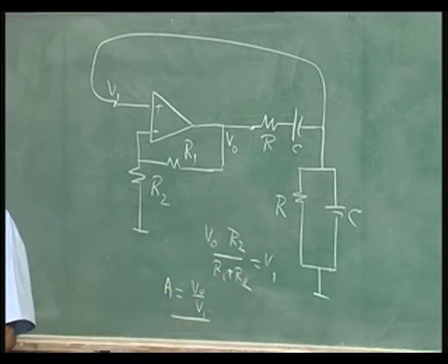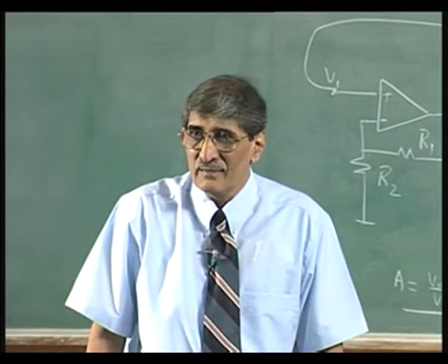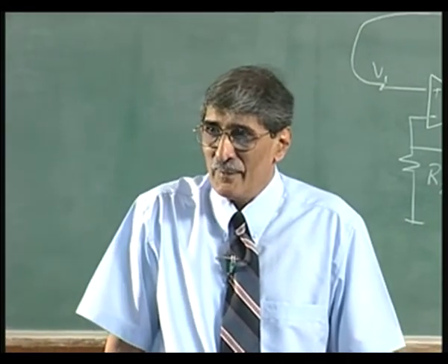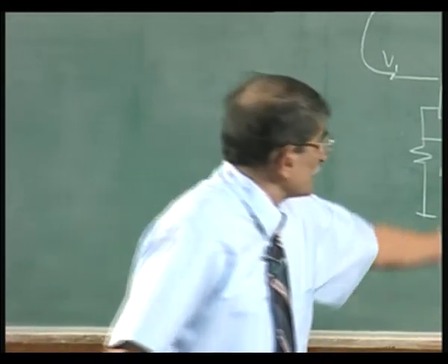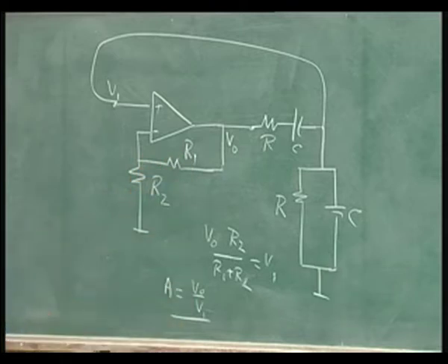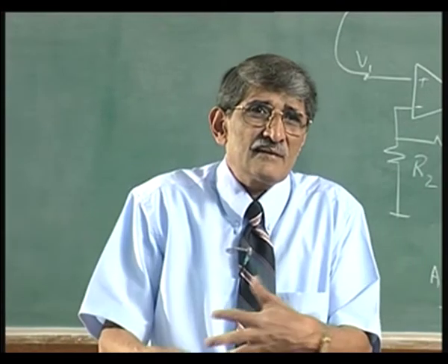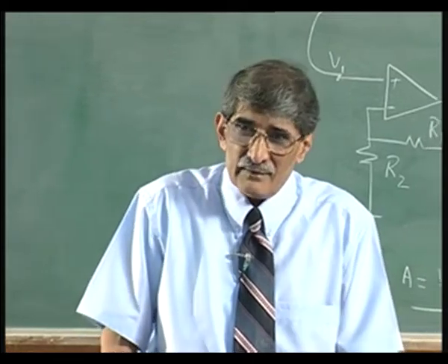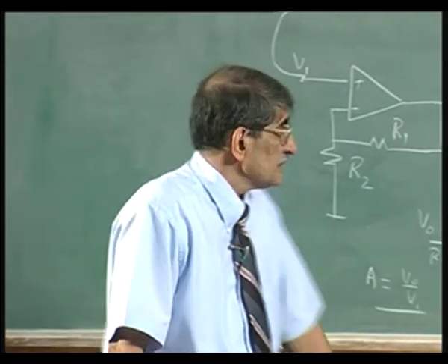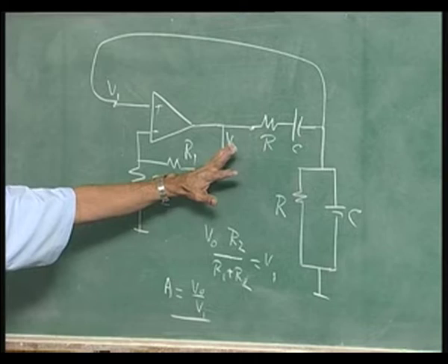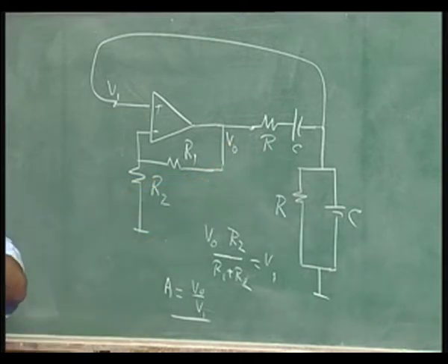But what will be the amplitude of this? You have no control. You put on the power supply to this op amp, it will turn on, you will see the amplitude building up. What is the limiting factor here? It finally is limited by the nonlinearities. When the nonlinearities set in, it is less than the supply voltage, some value it will take up.